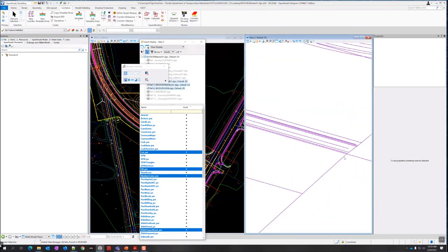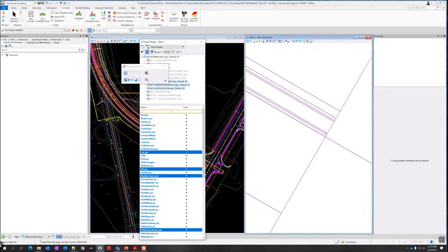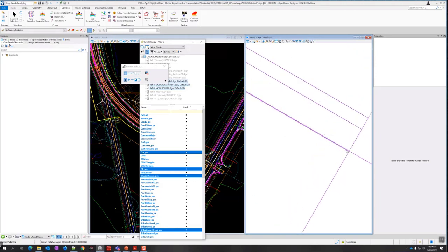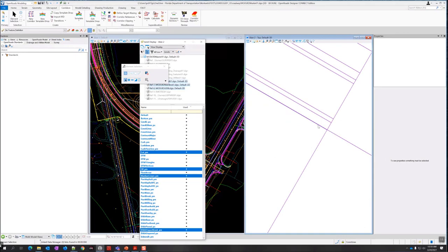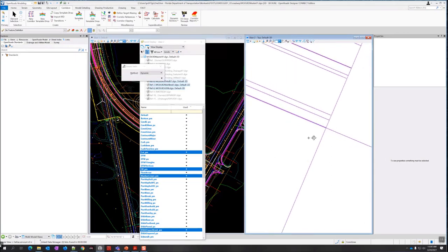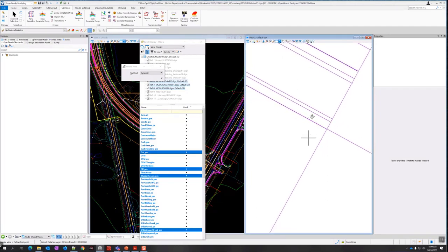Good to make sure that there's no horizontal difference. So if I change to top view, I can check, make sure there's nothing stacked on top of each other. So these look like they're on top of each other, but look, it's probably that 0.01 break. So that's all right. And if I just do a rotate view, I can see as I rotate to make sure nothing else is appearing to surprise me.